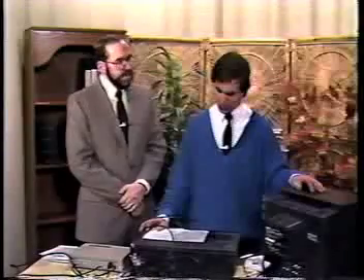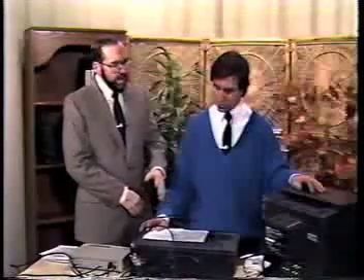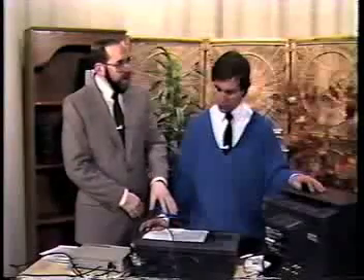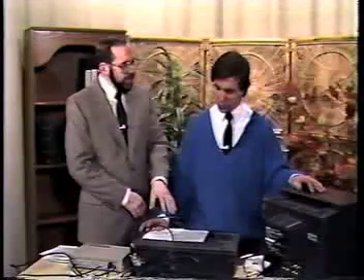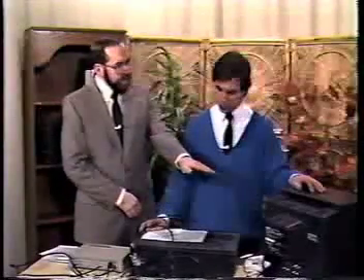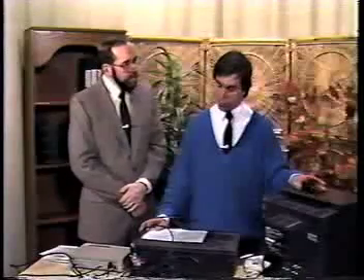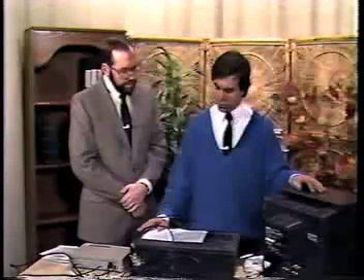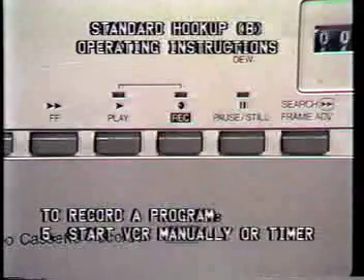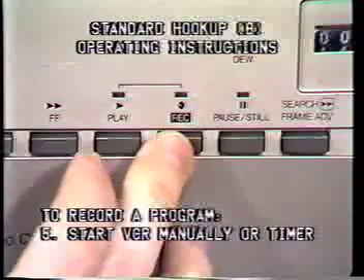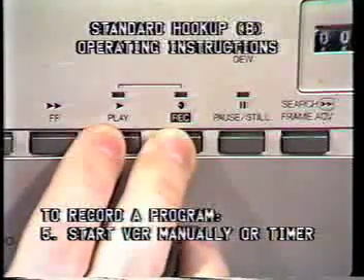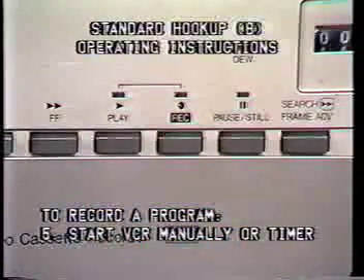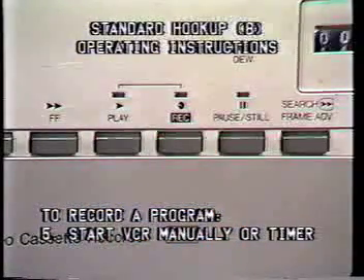So there are really two devices that would need to be fine-tuned here. One would be the VCR, perhaps if it's brand new and first set up, you might need to fine-tune this for the channels. Same thing with the TV. That's right, John. Both of them have a tuner, and the owner's manual should be consulted for fine-tuning the VCR. Sometimes they're a little tricky, so always check the operating manual. Finally, the last thing we need to do is to manually start the recording or to set the timer on the VCR according to the VCR instructions.